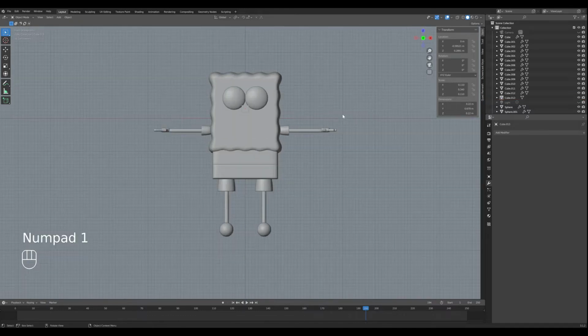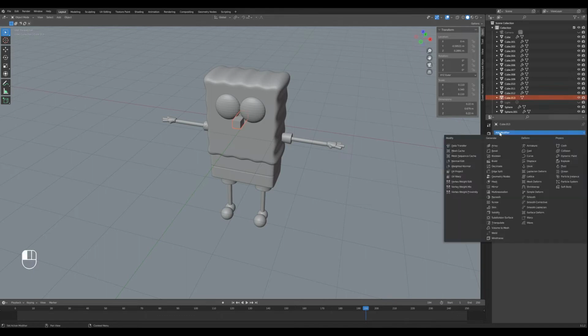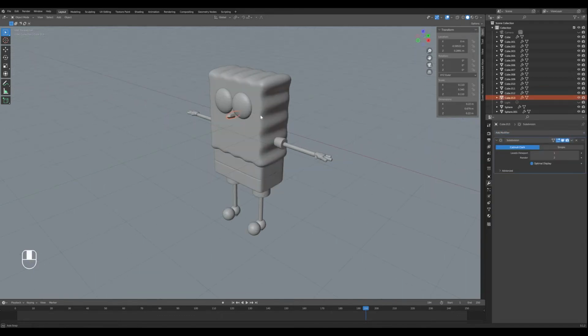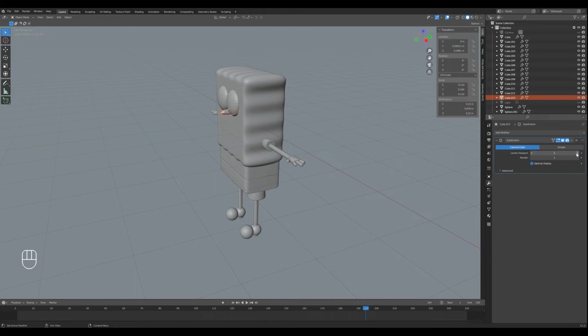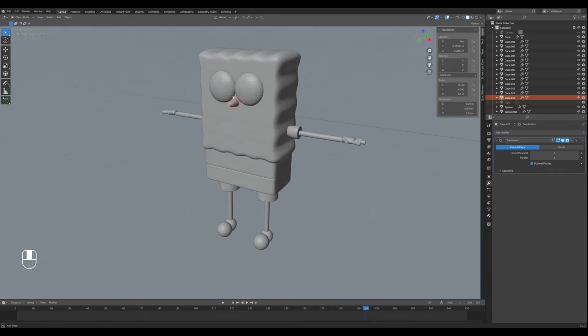And to get it out of the square shape, make it more rounded, not a circle, but let's see, click subdivision surface modifier, and we're going to click this up to the third level under levels viewport. Okay, but that's too pointy at the end, right?